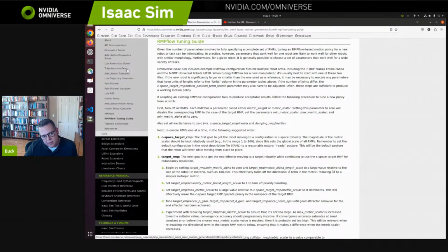You might say, move the end effector to a certain position and orientation, then make a linear move in joint space, make an arc move, maybe either slerping the orientation or having the orientation match the normal of the arc of the trajectory.